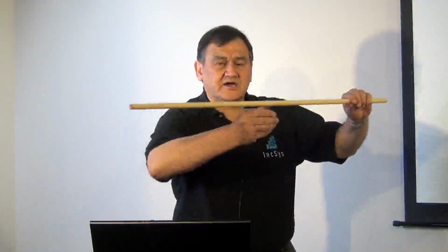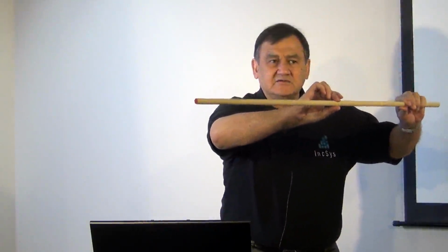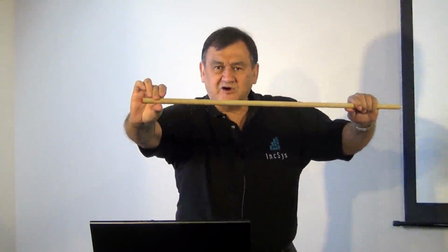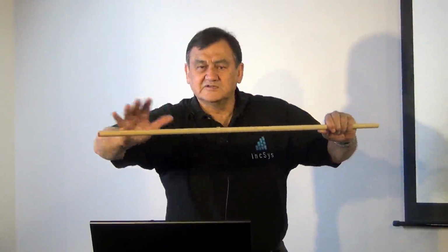The losses in the transmission system are relatively small, around 5%. So with active power, it's very predictable. If you have a transmission line and we're putting 500 megawatts in this end, I know I can't get more than 500 megawatts out at the receiving end. I'm going to get something a little, maybe 2-3% below 500. So from your SCADA point of view, you've got a good intuition. You will have a good feeling for how the real power is flowing in your system.